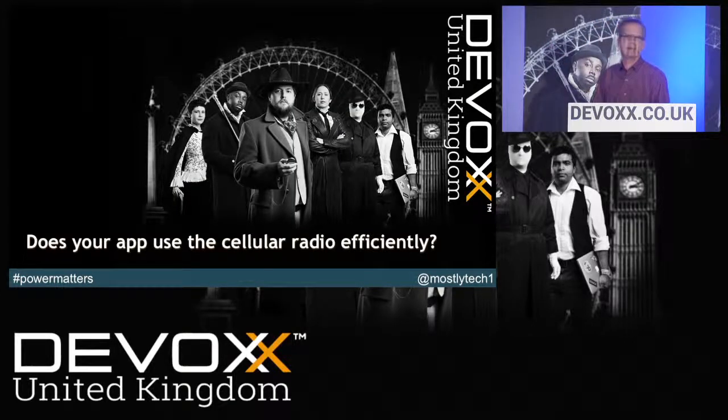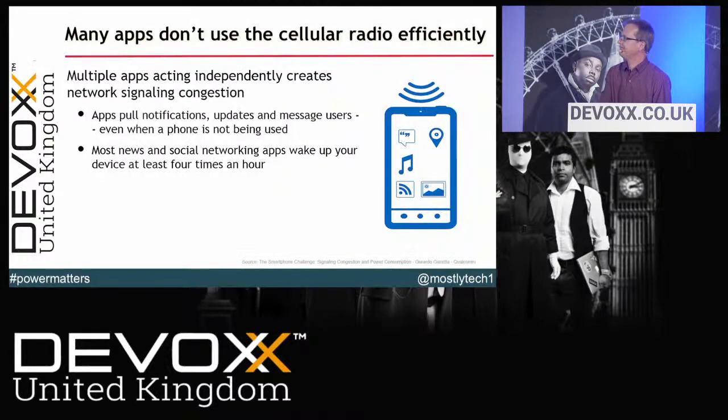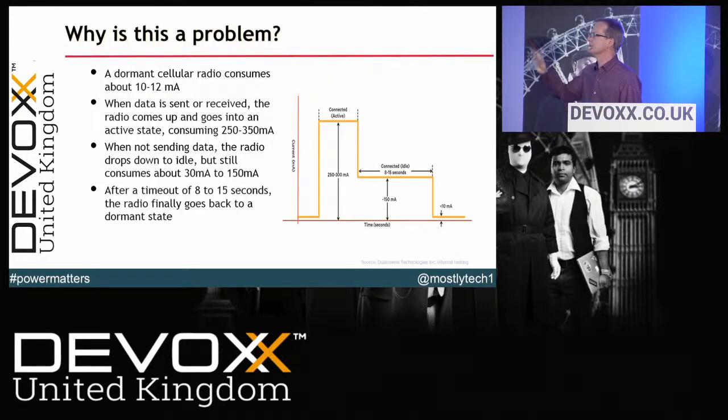Okay, so does your app use the radio efficiently? Things like social media, in fact most apps, are pulling notifications more than they need to. The reason this is a big problem is if you look at the way a cellular radio works, when it's idle, the power consumption is very low. This says 10 to 12 milliamps. I've seen even a modern device probably lower than that. When it goes into a full power transmitting mode, you're going to see a big spike. This chart is an older device, probably a 3G device. It says 250 to 350. You'll see later it's actually higher than that.